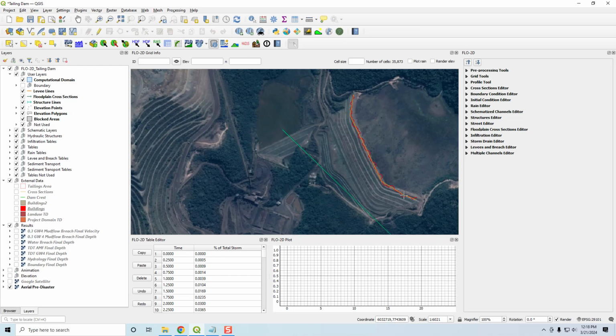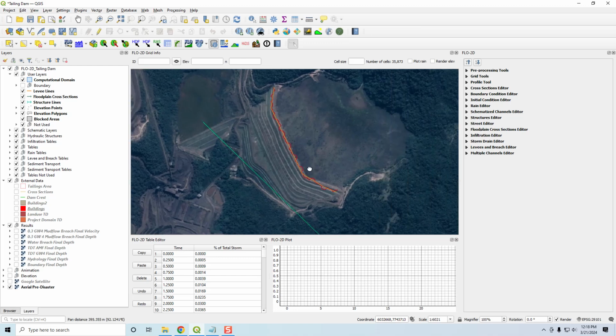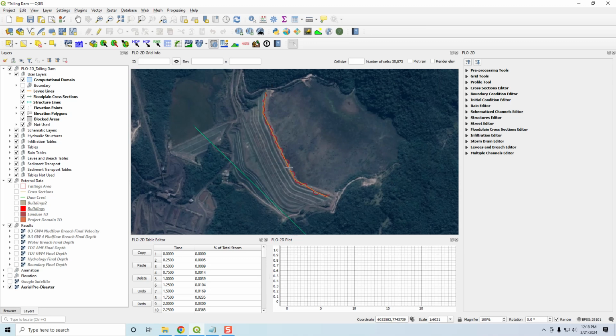So in this case, we show you how to set up these different events, but we always use this same fill because we know the volume of this event. We can set it up with the tailings dam tool, which is just a breach hydrograph that you put somewhere in here, or we can set it up with a levee and reservoir volume where you can just collapse the whole levee, or you can set it up with a point where you set the breach event to grow laterally across the levee at a predicted rate of failure. Or you can set it up as a stack collapse.